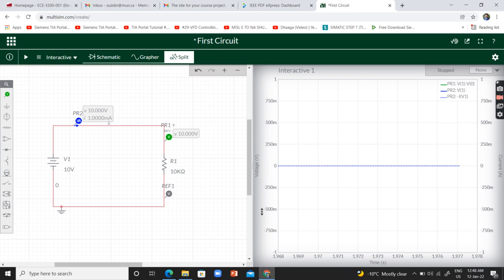Over here, we have two different axes on the y-axis. Here we have voltage and here we have current. So when you place your mouse over this part and scroll your mouse, it's going to change the y-axis setting. You can see over here, the time is going to expand or compress, right?